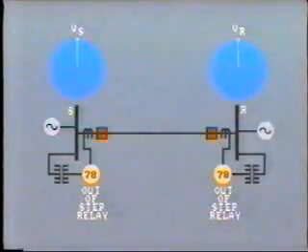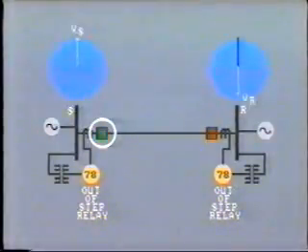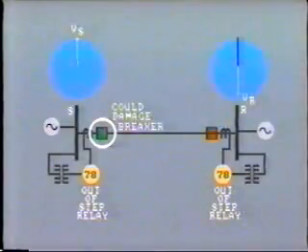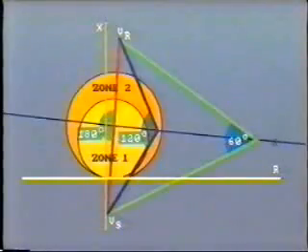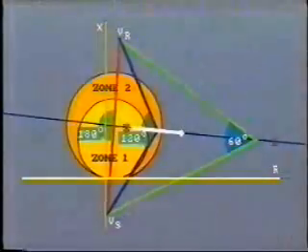Where the out-of-step relay is used to instigate tripping, the timing of the breaker opening is most important. If the breaker is opened at the precise moment where the two voltages are 180 degrees apart, then an exceedingly high voltage will exist across the breaker contacts, and this could cause breaker damage. For this reason, when the out-of-step relay detects the out-of-step condition, it will delay tripping until the measured impedance starts increasing again.